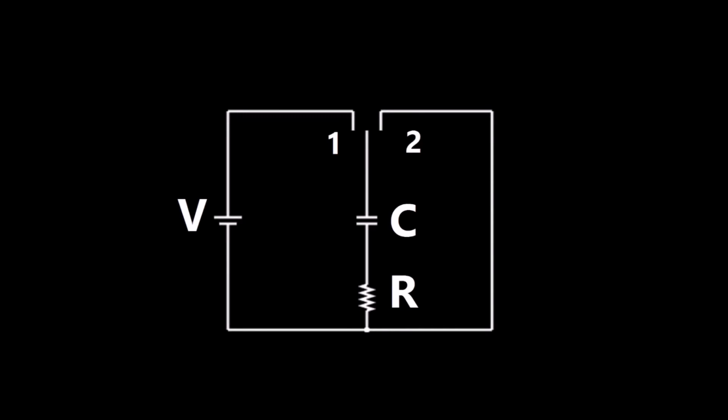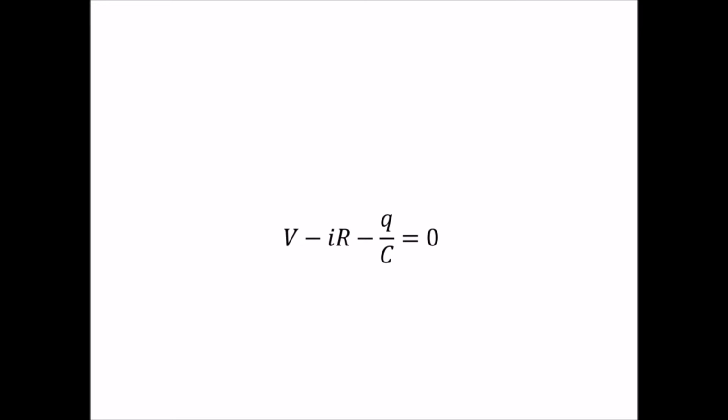Okay, so now that we have some idea about differential equations, we can derive some equations about capacitors. Let's consider a basic RC circuit with a switch. When the switch is in position 1, it'll be charging. Now we can consider KVL of a series circuit. From here we can divide everything by R. Take note that the current is the flow of charge.